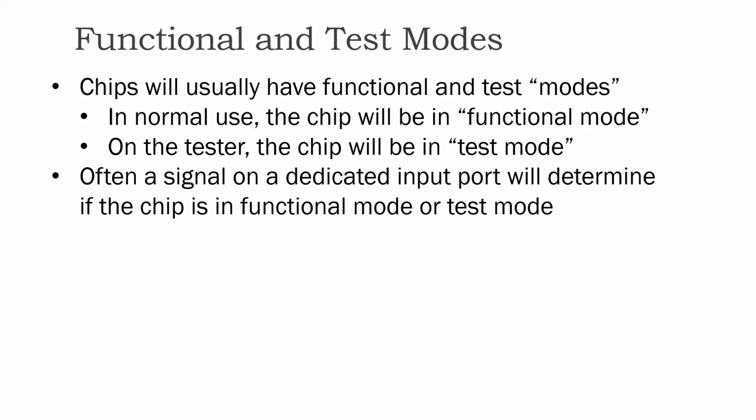Testing a chip is not trivial. A chip has many nodes, millions of transistors, hundreds of thousands or even millions of gates. There may be analog circuits, I/O circuits, any number of circuits. Any of them may have a defect, and testing has to be very thorough and exhaustive in order to ensure that the chip is truly defect-free. To do this, we usually have to add some additional circuitry to the chip for testing. The only purpose of that circuitry is for testing. There's no functional purpose for it.